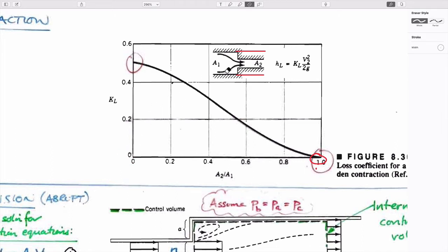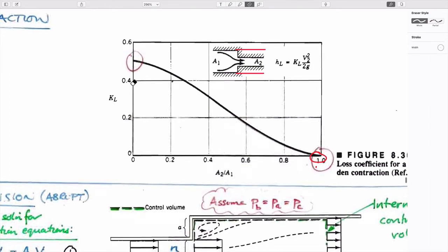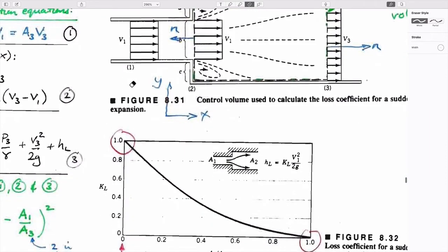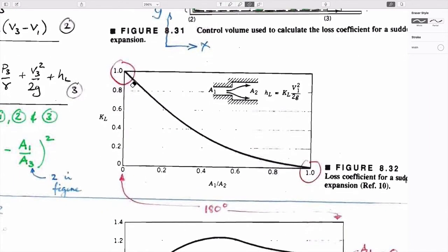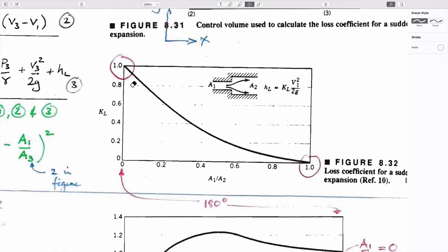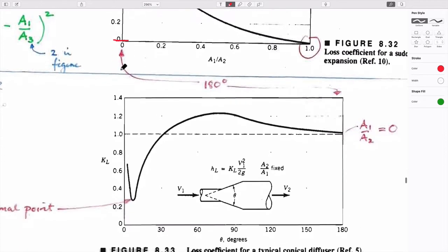And as you get a bigger disruption, you have a loss coefficient which approaches half. The same when you go exit from the relative areas. If you change the areas to be 1 again, so there's no change in the cross-sectional area of the pipe as you go downstream, then you'd expect there to be zero loss, and of course that's the case here. And as you have a bigger change as you go into an infinitely large tank, it approaches 1, as we saw in the previous cases.